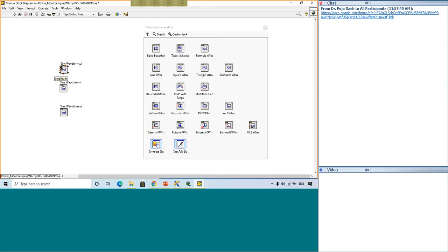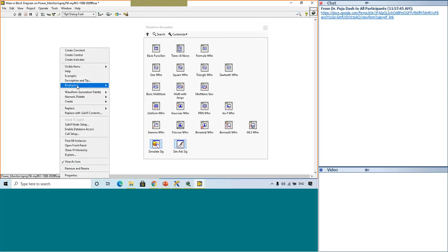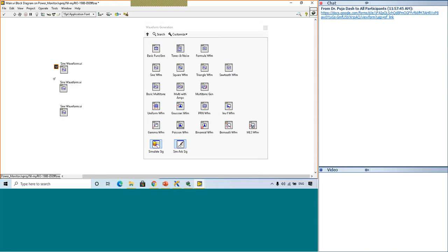And here you can see that this program has inputs. Since LabVIEW is based on input and output, you need to give some inputs to it. One is the frequency, and in the three-phase, we will assume that everything is going to have the same frequency of either 50 hertz or 60 hertz, whatever is better.